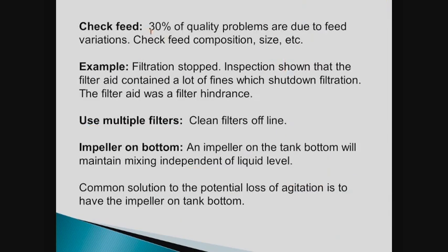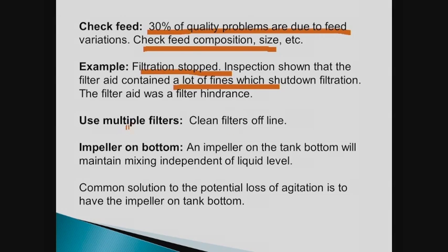You want to avoid quality problems in your feed. You always want to check feed composition. Obviously, we've already talked about filtration. You want to clean your filters offline. Impeller on the tank bottom, good idea. All right.